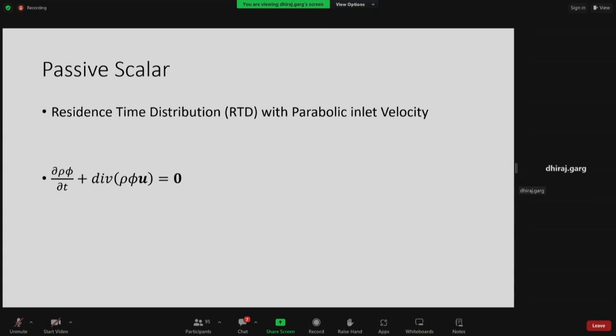So far so good? Sir, I want to ask one question. Yes. If we take the phi value equal to 1, how will we calculate the continuity equation or some other equation, because the phi value is varying? I'm not connected. Okay, elaborate. As I said, since this is a passive scalar, your flow distribution, pressure distribution, everything is already established. So they are not touched and you don't require to touch them at all. You are only solving for phi. Is this clear? Okay, sir.